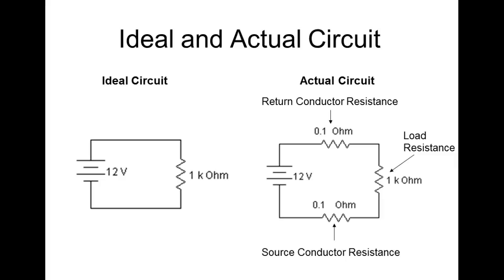And of course, what I'm trying to choose is the smallest conductor I can possibly choose. Why? Yeah, because of cost. You know, I could go in my house and run 6-gauge wire all through my house. I probably wouldn't have any trouble with it, but I'd be spending a fortune just for the wire, right? So what we're trying to do is size a conductor, the smallest conductor I can use, and support the load that those conductors are trying to run.